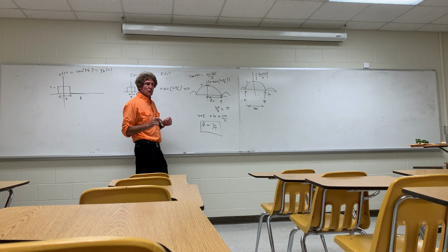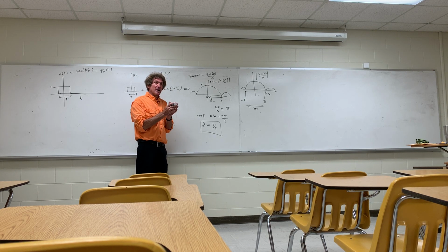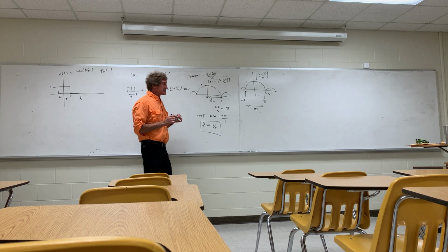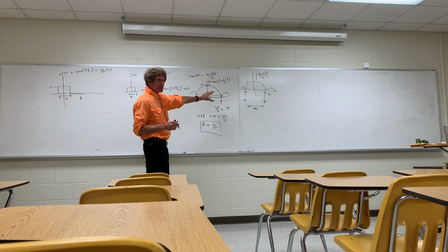With radar, when we talk about any type of beam width or bandwidth, it's always the half power points, where the peak power is reduced by half. Here, not so easily done. This is 1 pulse, that's the frequency spectrum. Y'all follow me on this one?